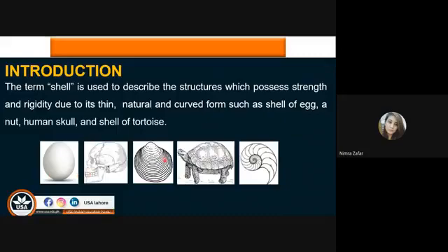These shells are very thin. All of these perform their respective function. They have their strength due to their thin membrane type material. So the shell structures are basically made on this concept that they are thin, lightweight, provide structural support as well as play their role as covering of a building.